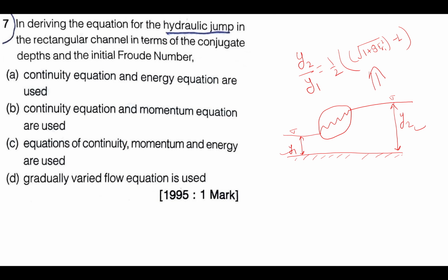If anyone is interested, please let me know through a comment. I will explain more, with the full derivation. So now let us discuss. One equation you can use here is the momentum equation, and another equation you can use is the continuity equation. Continuity equation we can apply because here the mass is conserved. So if we take the cross sections, the inflow discharge and outflow discharge will be the same. So we can apply two equations: one is the momentum equation and another is the continuity equation.